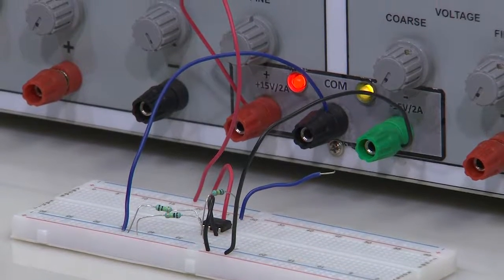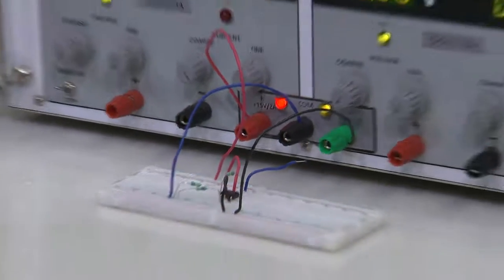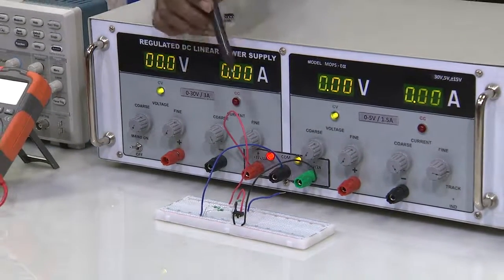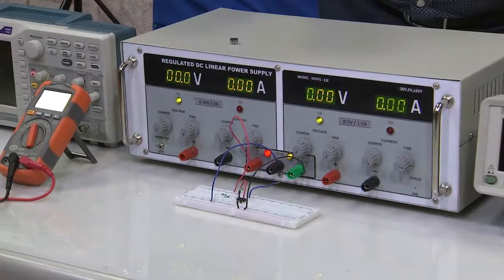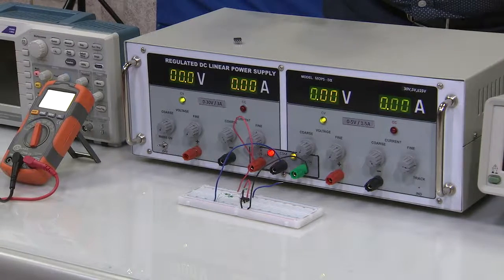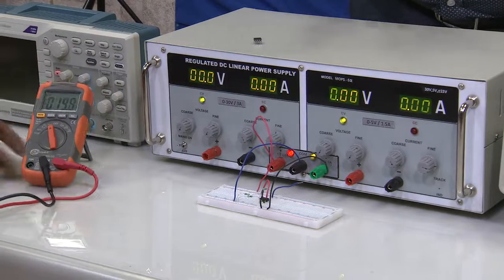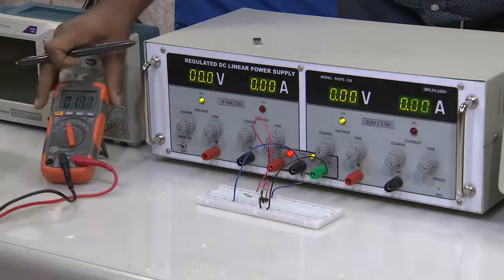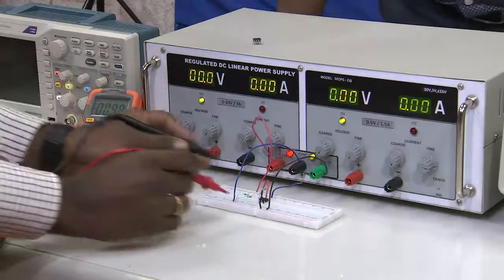Now, we are measuring the output voltage. Both the input terminals are grounded. So, now we are understanding the output voltage. From where can we measure the output voltage? We can measure the output voltage at pin number 6, or between pin number 6 and ground. So, what is the output voltage? Let us see. Again the multimeter is in DC.